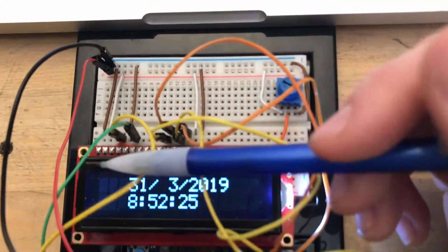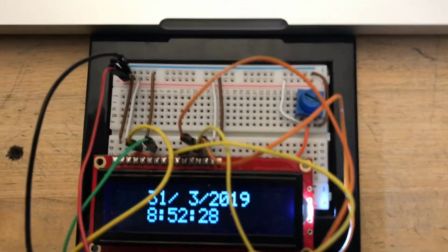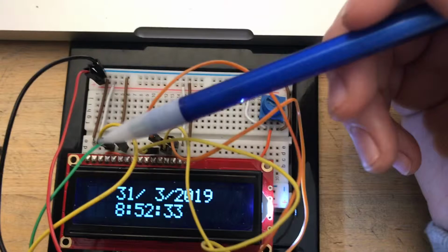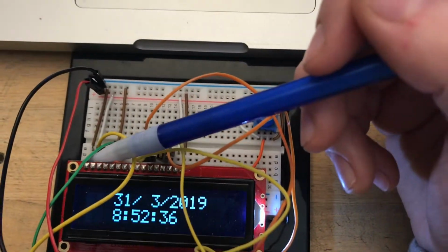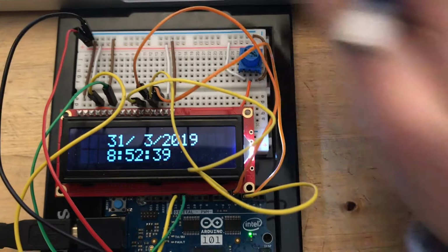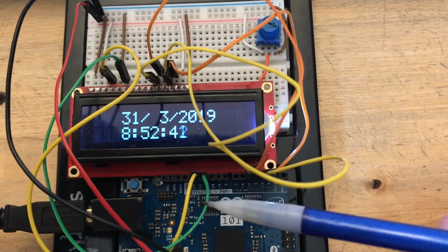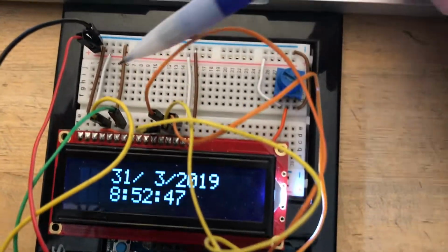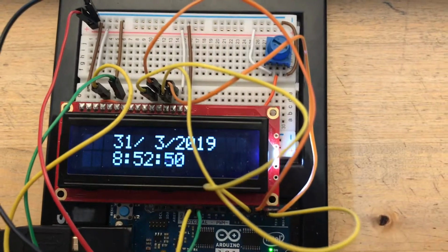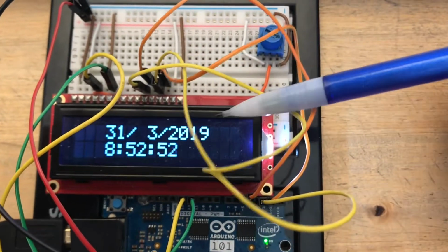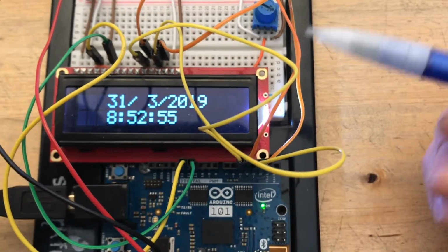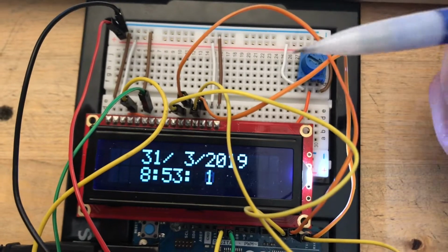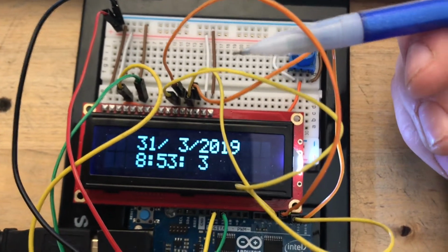Then we get to this brown wire here. That's going to also ground the board. And then here is this green wire here. It is going to start a signal for reading or writing data, and that's going to be connected to pin 11 on the Arduino. We're going to skip a few spots down by this yellow cable here. This yellow wire is data bus bit number 4, and that's going to connect to pin number 5 on the Arduino board. This orange wire here is data bus bit 5.